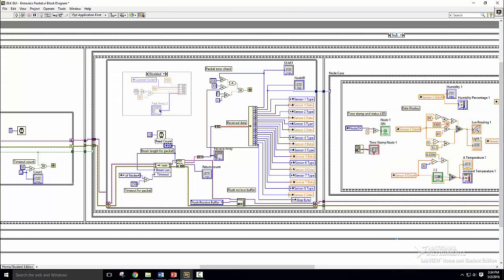And now going back to the block diagram, the first thing that has to be changed is the data will come through this string byte and be set to an array. We'll have to change this cluster size though for the array, so we'll simply right click and get cluster size and change this to 21. So that has added 2 new bytes to the bottom. So we're going to first break the line for the stop byte, as it is now changed. And we're going to attach the last byte to the stop byte.